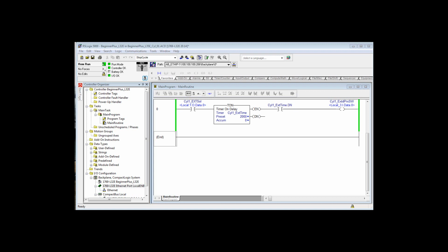We started out real simple, and we show the state of the extend solenoid. In other words, in the very first instruction it says true if on. If bit 0 is on of that output module, then we have told cylinder 1 to extend. Those of you that are more used to the older format for programming that was more true to electrical, you have to get adjusted to this style where we put loads in series.